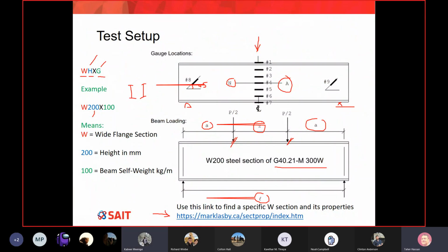And when you were saying use E equals 200,000, is that the value we're supposed to use, or are we going to get it from the graph? No, you cannot find the value of E. Please use a value of 200, which is typical for mild steel. This will be the value for the modulus of elasticity, 200,000. It's 200,000 megapascal, or 200 gigapascal. That's the modulus of elasticity.